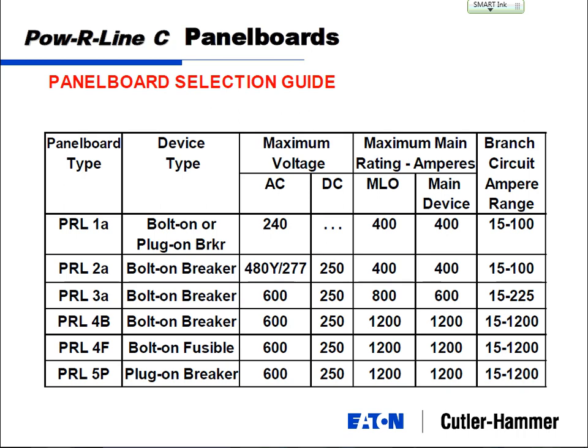The trip unit itself is looking at the current and creating its own waveforms inside the trip unit. With the creation from normal current, and you're creating a digital model inside the trip unit, you have much greater selectivity on your tripping curves.